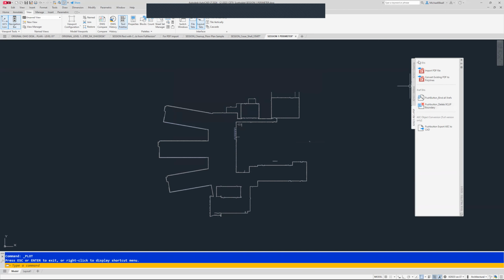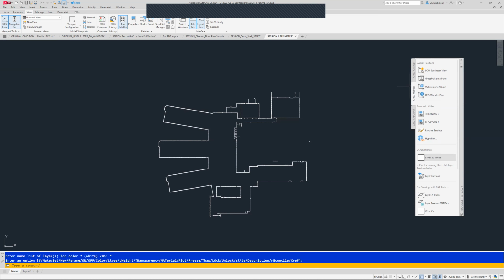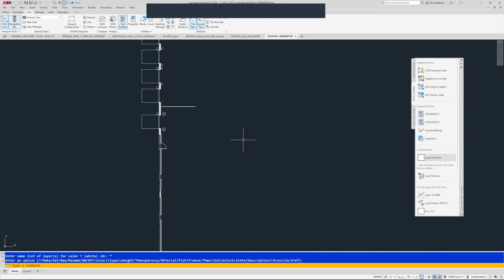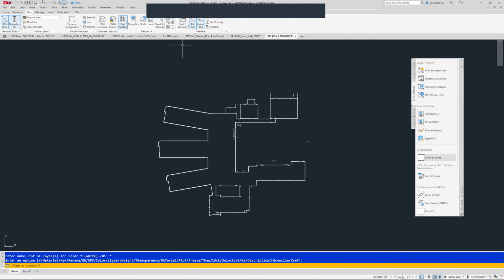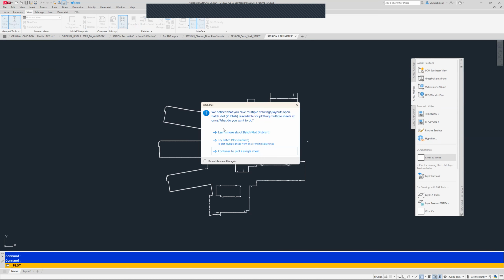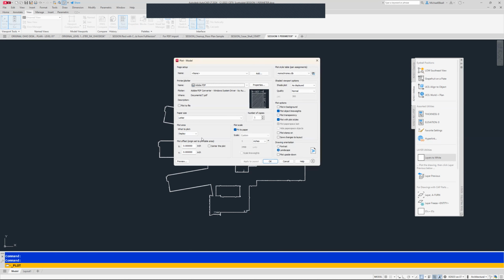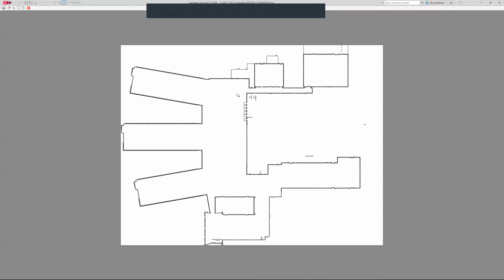Let me show you a couple of buttons, and I'll circle back to the monster drawing thing. Back here in cleanup. Oh, I guess it's under utilities. In utilities, I have a button here that just says layers to white. If you cannot get monochrome to monochrome, click that button. Everything turns white. And you go to plot and it's like, all right. Monochrome's good. Display's good. Here, let's go to extents, do the preview. Yeehaw! You got black and white.